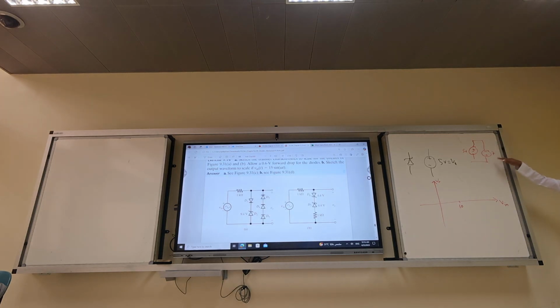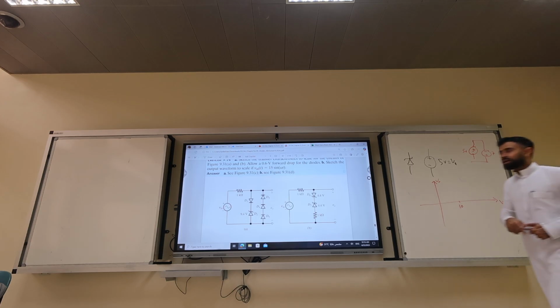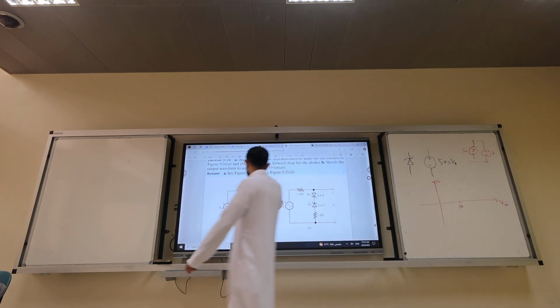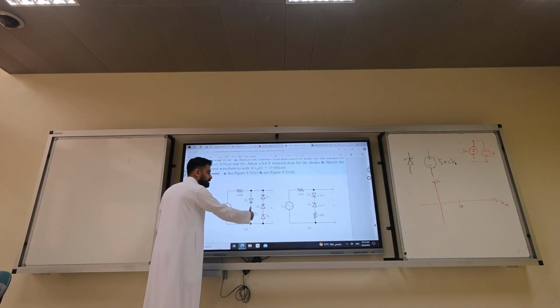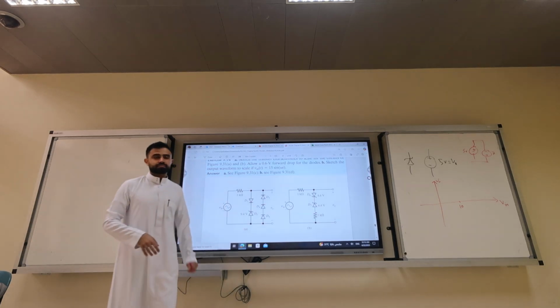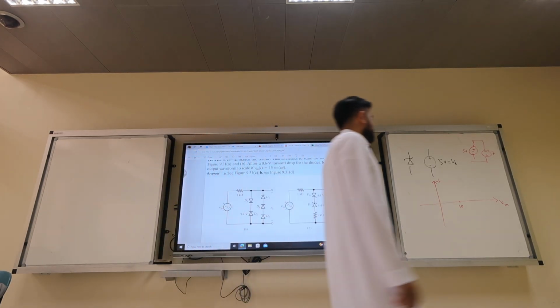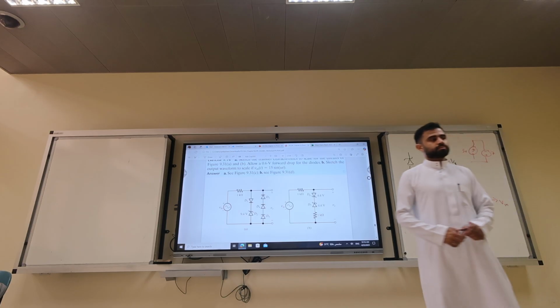No. It is the same as connecting a car jumper cable and flipping the battery, and it blows up, the same thing. You cannot enforce 2 voltages to be at the same time. Can you enforce 2 pressures to be at the same time? You cannot. So same for electrical engineering. So by design, question in the final exam, can those 2 branches be active at the same time? No.